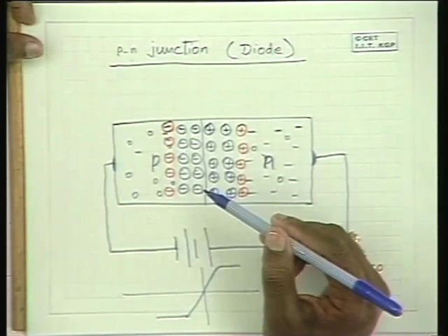So this is known as avalanche multiplication, and the phenomenon is known as avalanche breakdown, because of which there would be a large amount of current flowing. With a very small increase in voltage, millivolts of increase in voltage, you have a huge amount of current that flows.